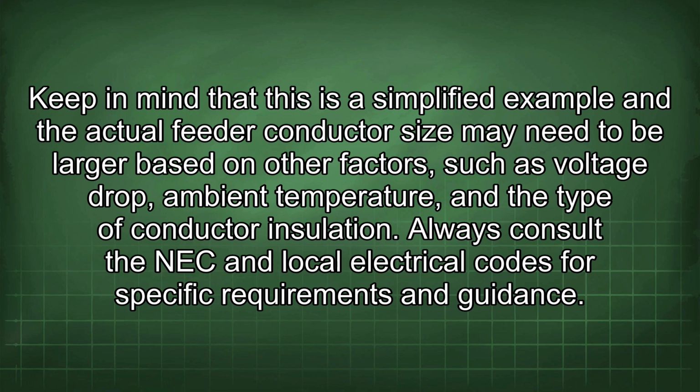Keep in mind that this is a simplified example and the actual feeder conductor size may need to be larger based on other factors such as voltage drop, ambient temperature, and the type of conductor insulation. Always consult the NEC and local electrical codes for specific requirements and guidance.